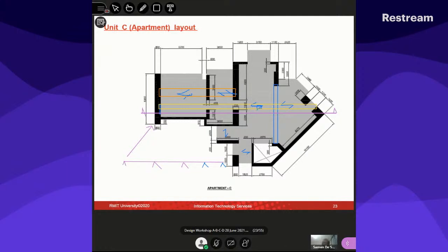I'll just quickly do that for you. So you will be having a little beam here as well, mind you, very similar to these areas. And then, of course, if I were you, I would be putting about 2 H beams here, and I will make this particular cantilever part not cantilevering, but actually simply supported through these 2 beams.